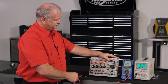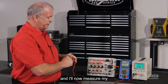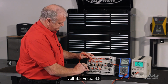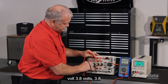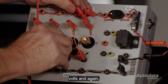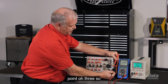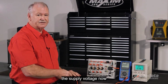What about voltage? I'll turn my circuit on, put my meter on voltage, and I'll now measure my voltage drops. 0.3 of a volt, 3.8 volts, 3.8 volts, and again a little over 3.8 volts. My supply voltage is 12.03. So we can see the sum of all the voltage drops equals the supply voltage.